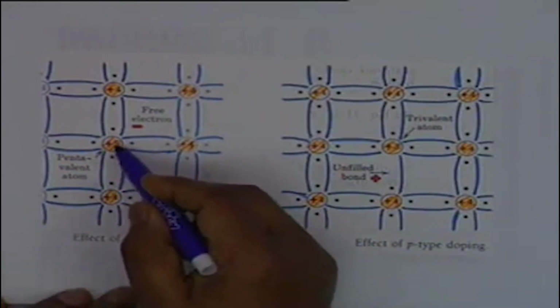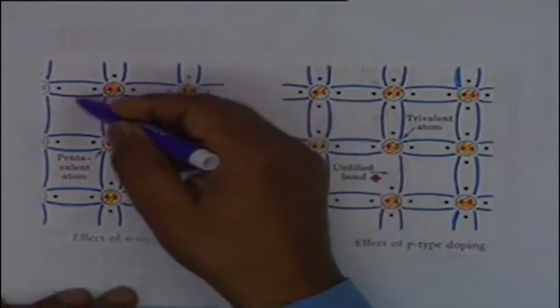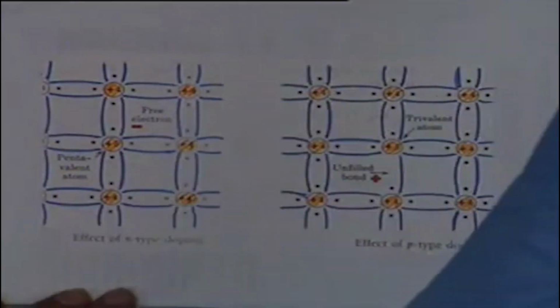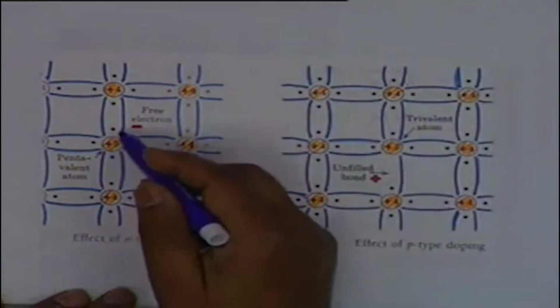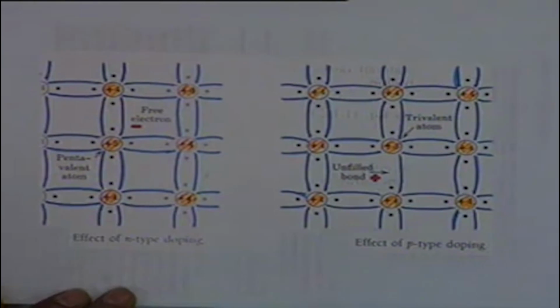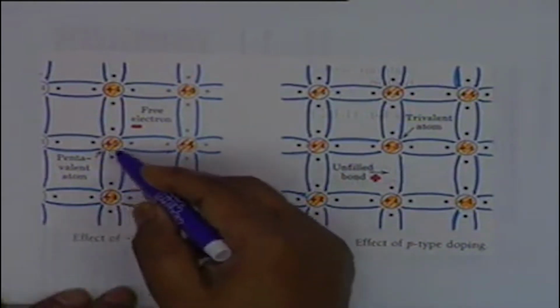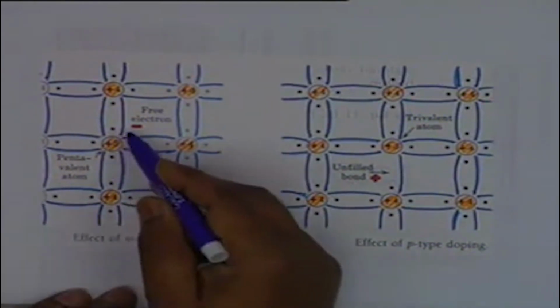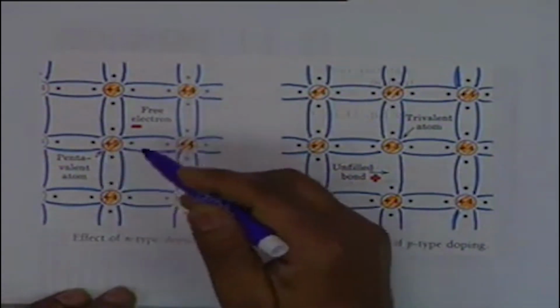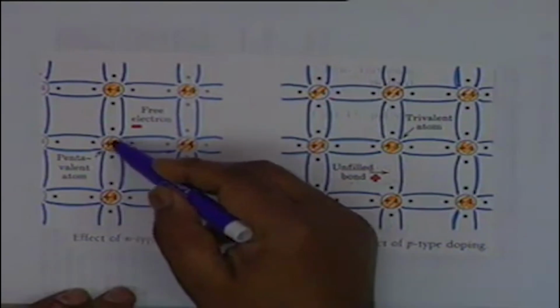And when it takes up a position, the neighboring silicon atoms don't know that it is arsenic. So, they extend their hands, and 8 such hands are filled up. One extra electron is knocked out because 8 electrons make a stable configuration. The 5th one that this arsenic atom had extra is knocked out.